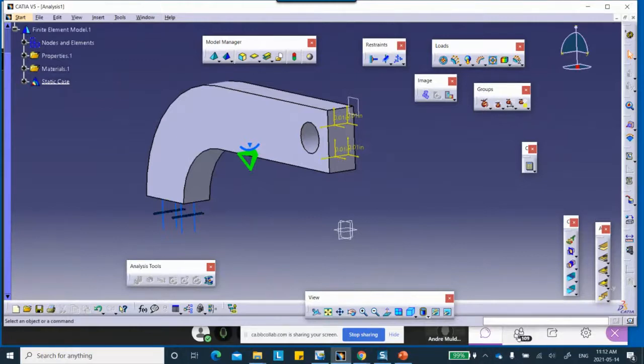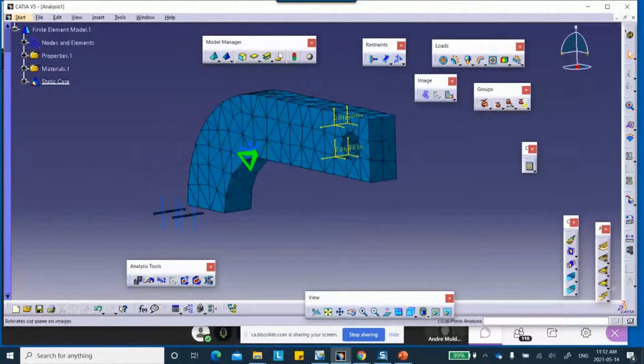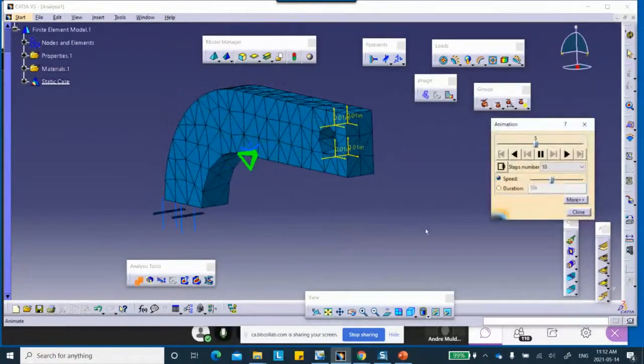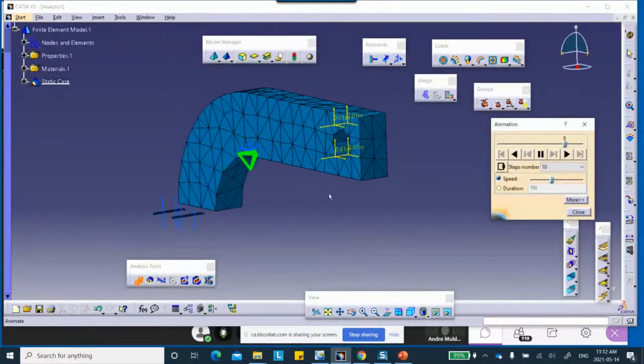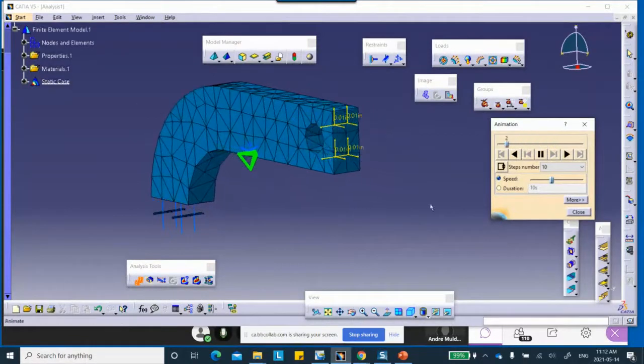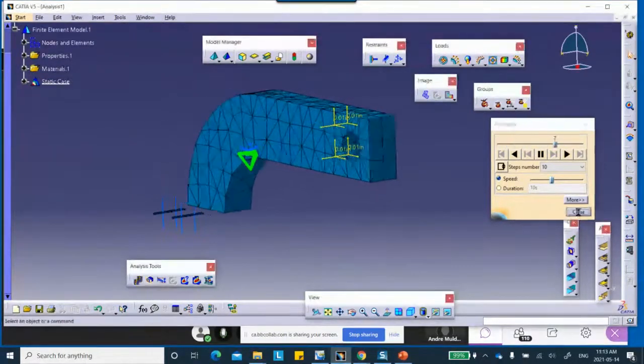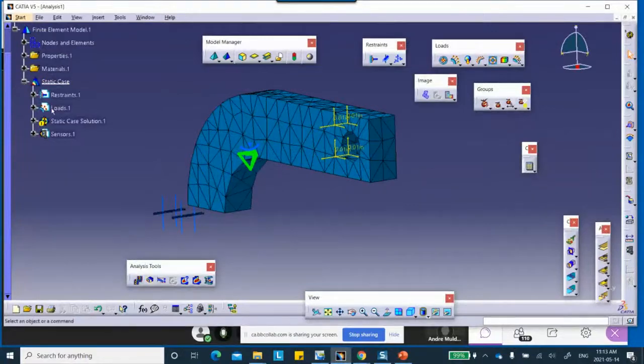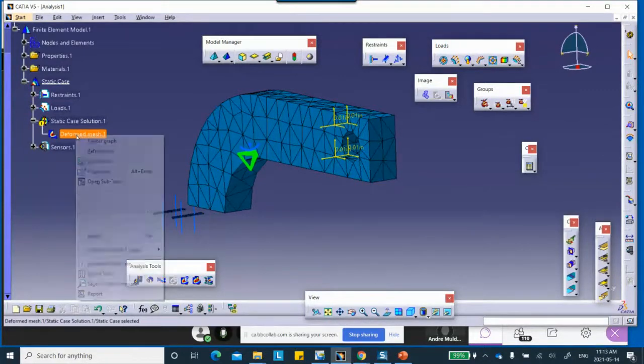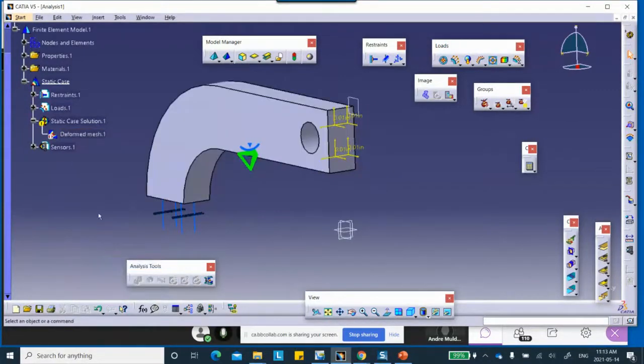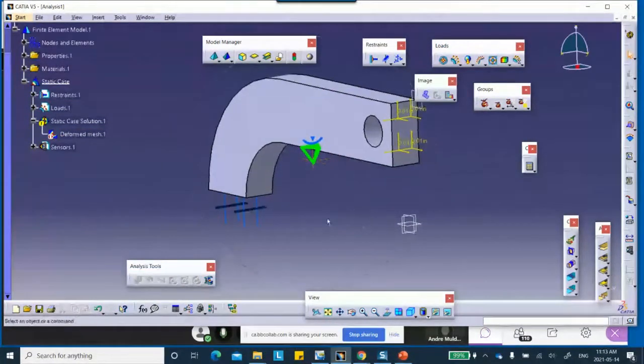Any suggestions? CATIA sometimes can help you. Plot the deformation. It moves as a rigid body. It's like a fridge. Wheels at the bottom, wheels on the side against the wall. It can still move. So what we need to do, this is the 1, 2, 3 rule, but the 1, 2, 3 rule is not always 1, 2, 3 rule. You have to fix it. Basically, 1, 2, 3 rule is fixing it in a way that doesn't give you artificial stresses.